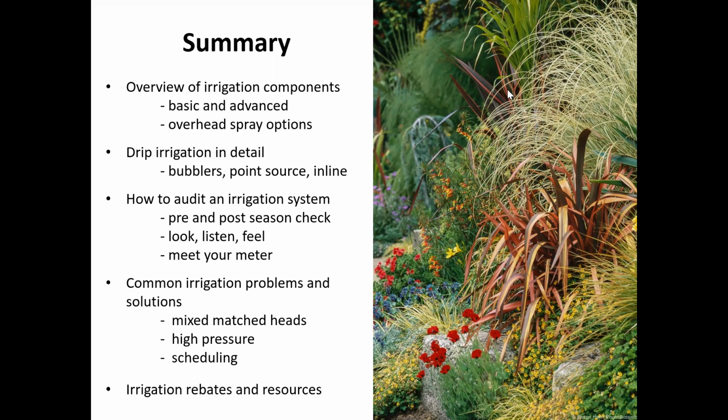So when you're setting it up on the controller, the duration is just the amount of time during that one instance. It's not going to know the overall added amount of time and water that's being applied. That's what you would have to do. Unless you have a smart controller, you're literally telling it exactly what it needs to do and how much. And that's the importance of understanding the difference between the cycles and the duration.